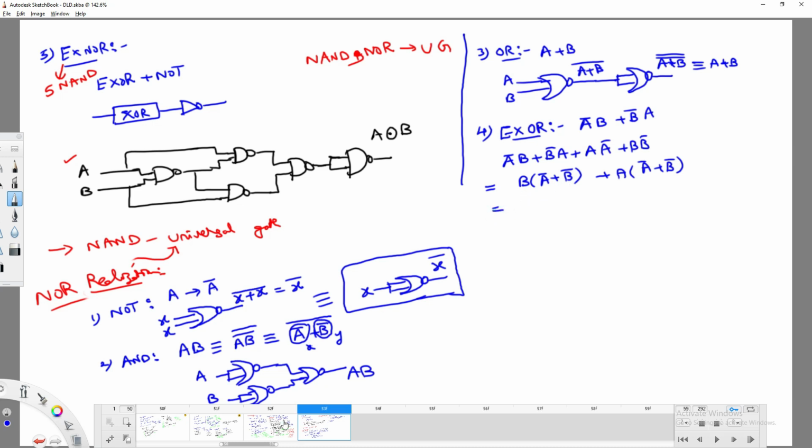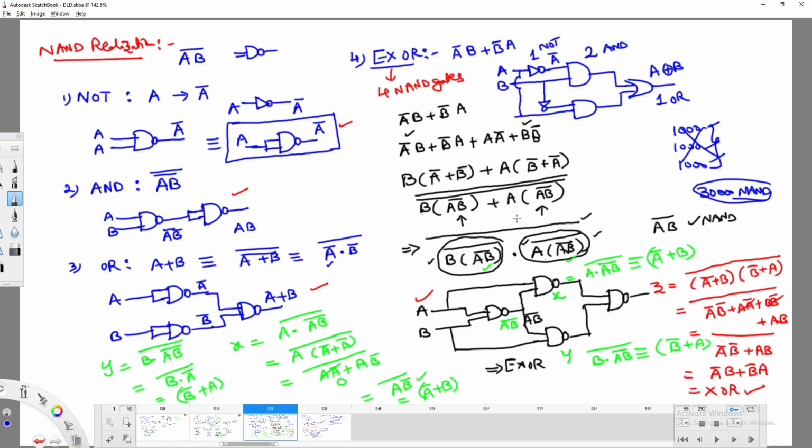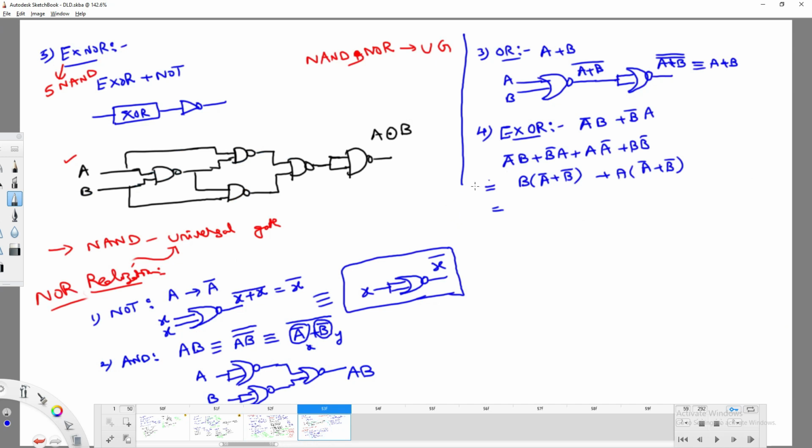Earlier, I required to represent it in the form of sum of products because it is a NAND relation. Now, to represent this with OR gates, it requires an OR and AND relation. So OR and AND means what? That should be compulsory product of sums, right? So I am writing it like this: A complement plus B complement into A plus B. Is there any problem? No, nothing.